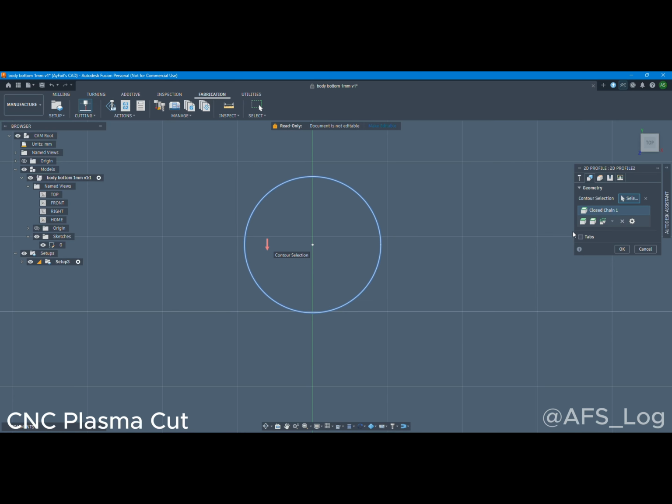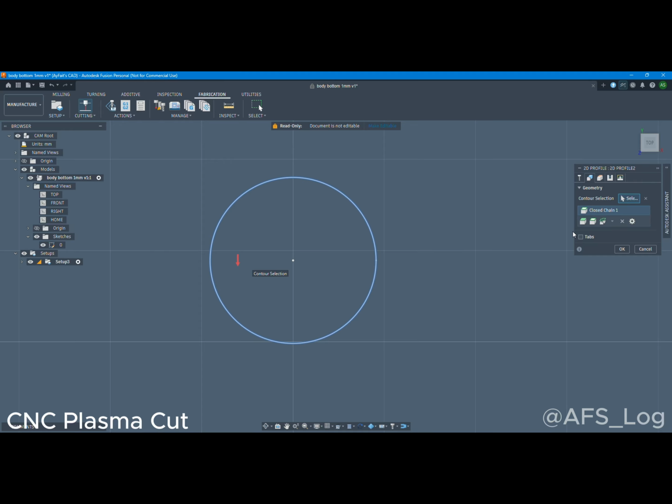That is one. Then secondly, what this means is the side of cut. You are telling the nozzle, the CNC machine, to make sure that the nozzle is moved in a way to compensate for the size of the circle, which means it's going to take into consideration the kerf width, so as not to cut this hole too big. It has to make the compensation from inside the profile.